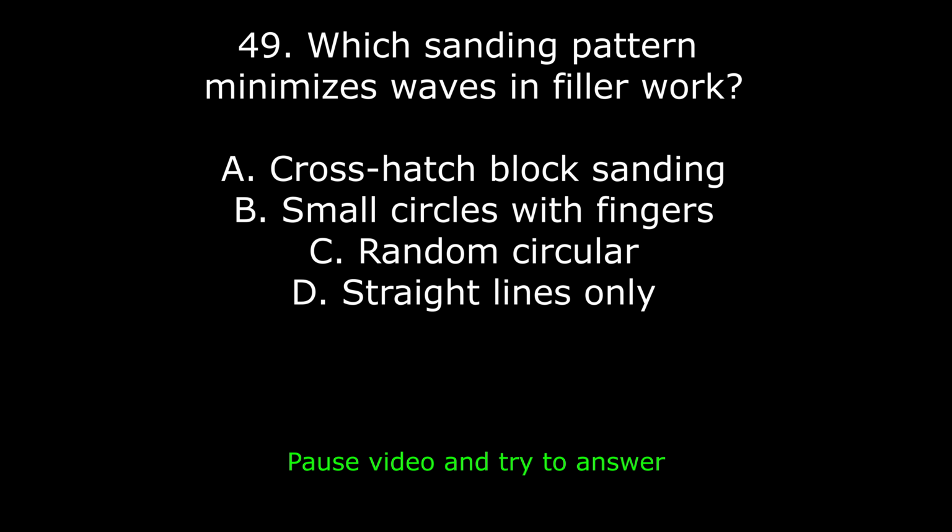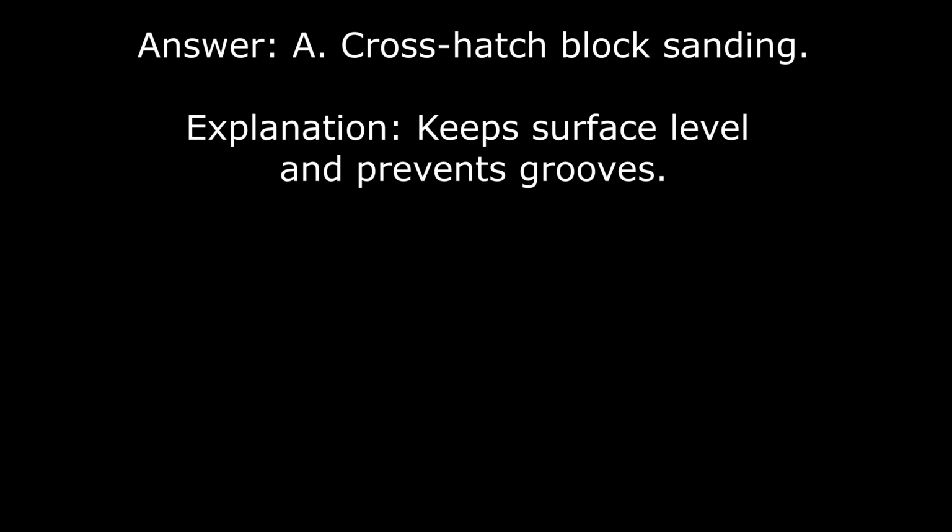49. Which sanding pattern minimizes waves in filler work? A. Crosshatch block sanding. B. Small circles with fingers. C. Random circular. D. Straight lines only. Answer: A. Crosshatch block sanding. Explanation: keeps surface level and prevents grooves.